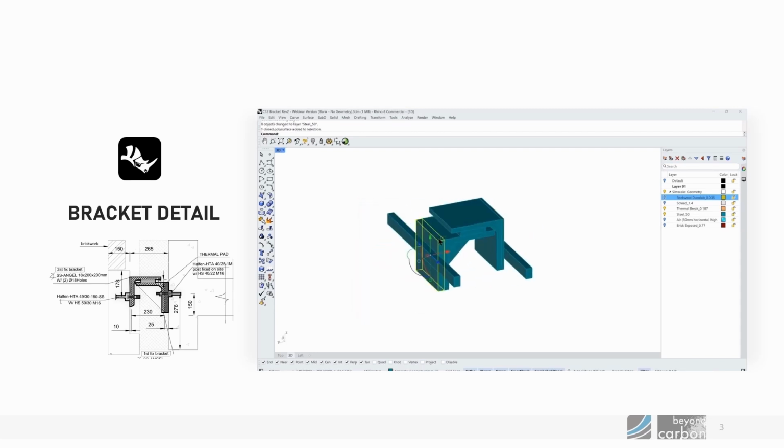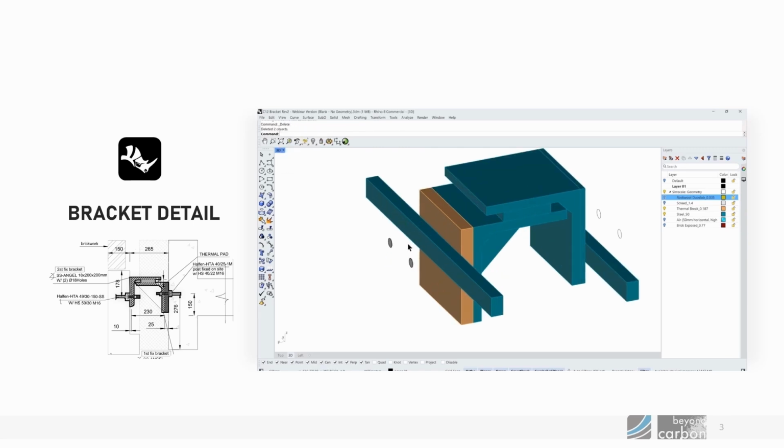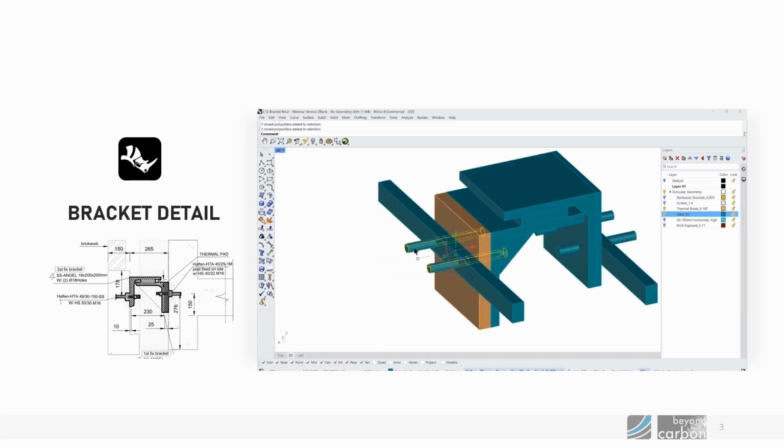And now you can see how we're going to include an intersecting object like a screw that's going to go through the steel plate and through the thermal break, and how we're going to account for that using face split and then brep joining them back to make sure they're closed and solid. So the screws are being assigned to steel, and now they are going to be split in the places where they intersect and then joined back.